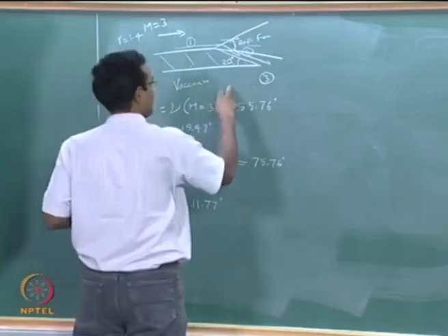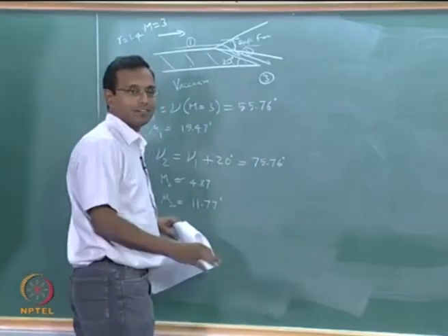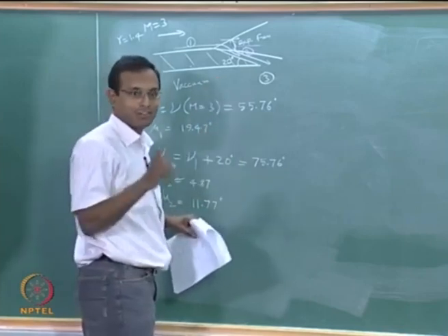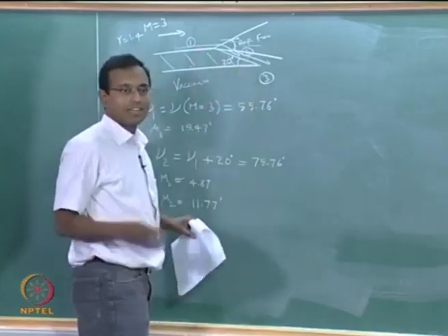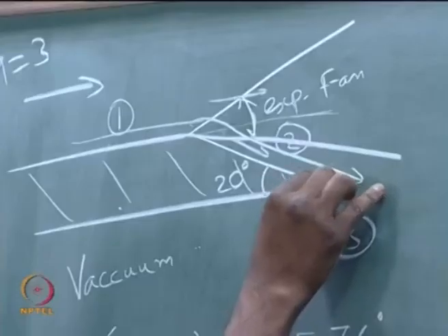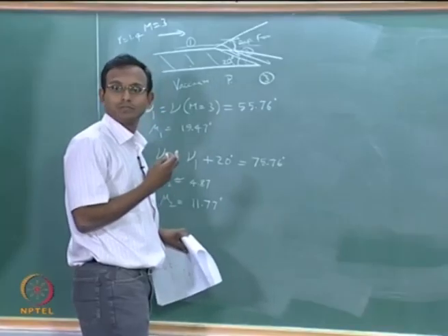Now, the next thing is, we have not given any angle change, but you are given pressure outside. We said in gas dynamics there are two types of boundary condition, velocity direction and pressure. We have been using velocity direction till now, suddenly we are giving a pressure boundary condition. If I give a pressure boundary condition here, what should it be? I have to just go and find what is the pressure here. It so happens that P is 0.